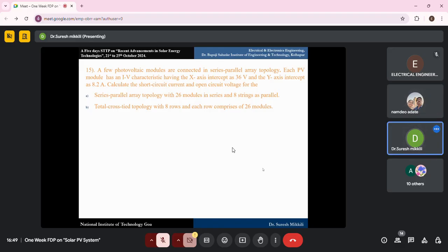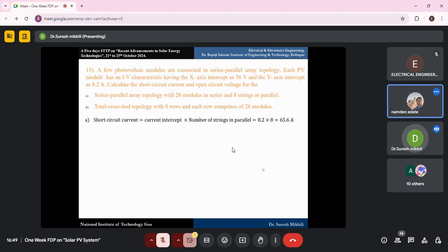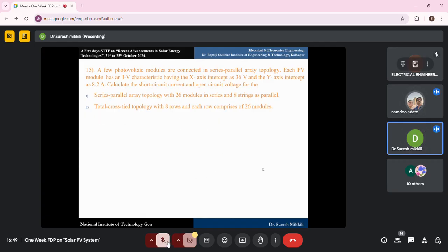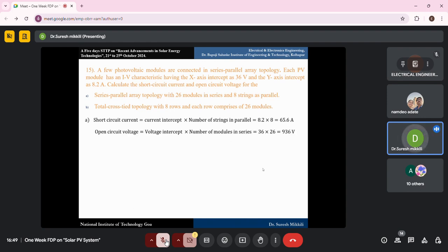So now series parallel, 26 modules in series, 8 strings in parallel. How much will it be? So total voltage, 936. You tell me the current. Current is 65.6, correct, madam. Then voltage is 936, correct.